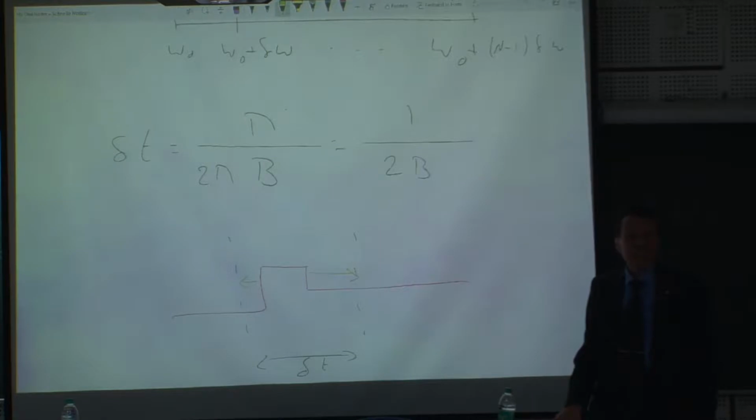So if you have, say, 10 giga, it is 10 to the power 10. So 1 over 10 to the power 10 is 0.1 nanosecond, right? And if you consider this in conjunction with the speed of light, irrespective now of the slowing down due to epsilon r, but imagine that it is free space, you can also calculate the corresponding delta x.